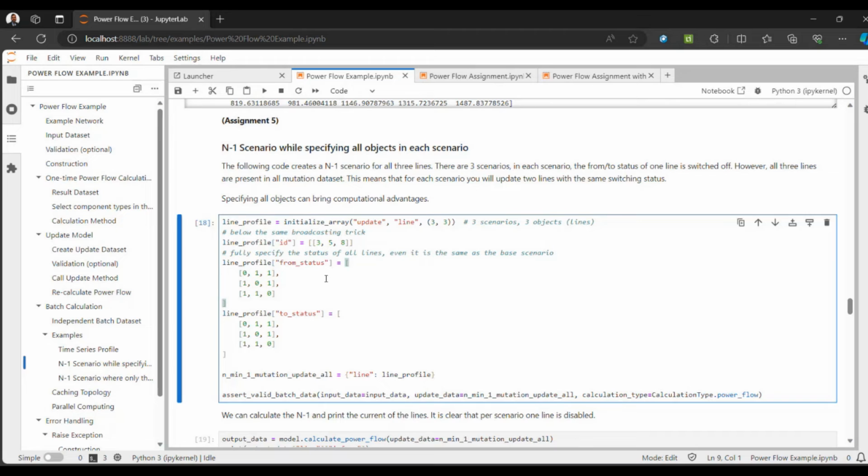In case anyone does not know, the n-1 scenario or contingency analysis is a special situation where we turn off each of the lines of the grid for each of the scenarios and find out the worst possible case among all of them where the grid fails.